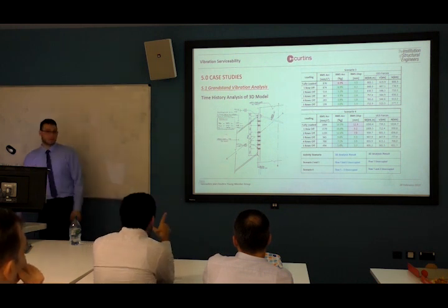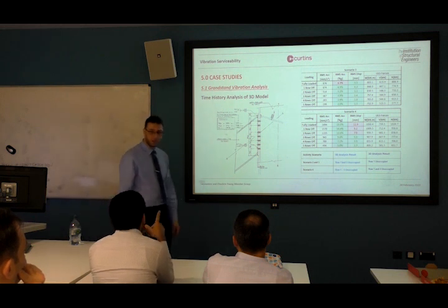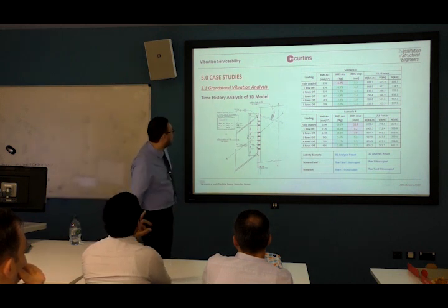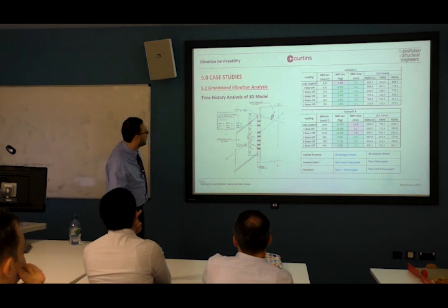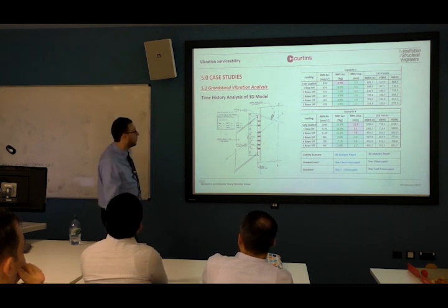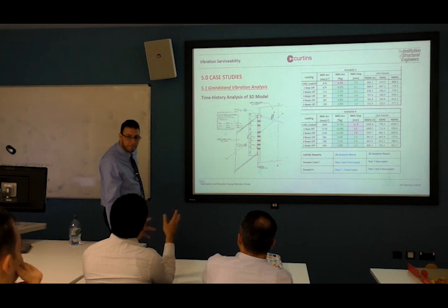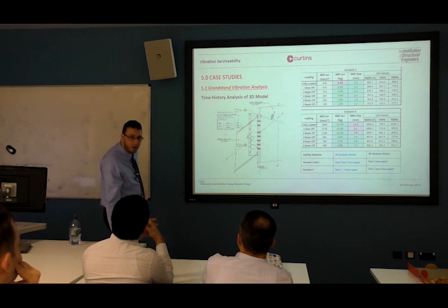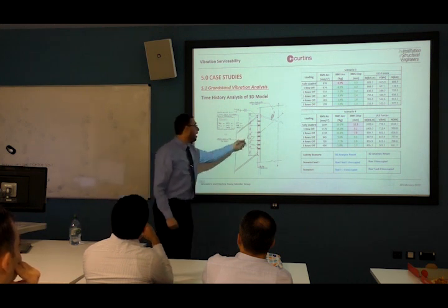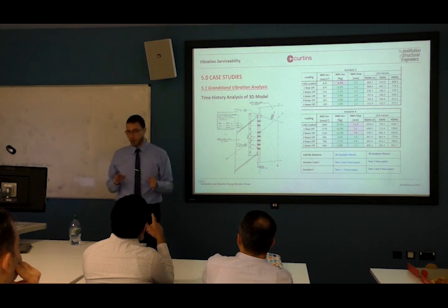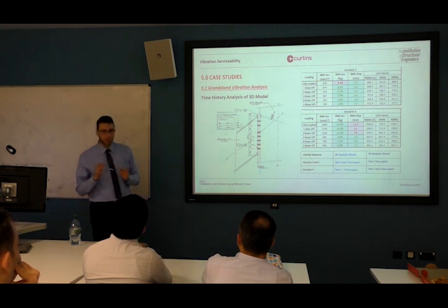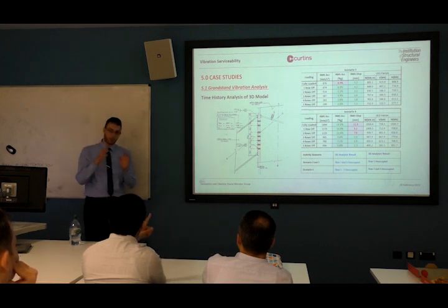Excuse me. Can I ask you regarding the connection now? Because some books and technical notes suggest that when you model for vibration check, you need to change the connection from pinned, even if on site or in reality it's a pinned connection, to rigid connections. Was that the case? No, this is not the case. It's in modeling, you're right. Yes, in modeling.